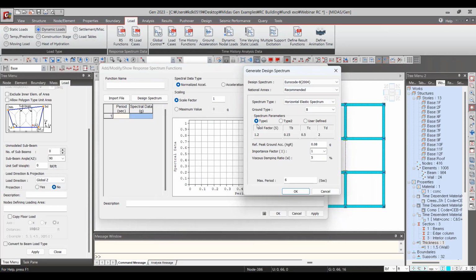And as we specified in the seismic load, we are going to select type 1 for strong seismicity. So we are going to select this default value, but we need to calculate this one separately and input the value here. And for the importance factor also we selected 1.2, but for very important building we go to 1.4, like hospital and power plant building we can select 1.4.